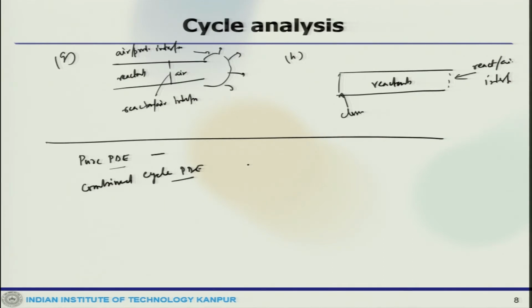Adding a PDE to the flow path of a ramjet or scramjet would make the engine capable of operating at Mach 5 or higher. Or you could have a hybrid PDE, which uses detonative combustion in place of constant pressure combustion, usually in combination with turbomachinery. So, this could again be of two types. There could be a hybrid turbofan PDE, or